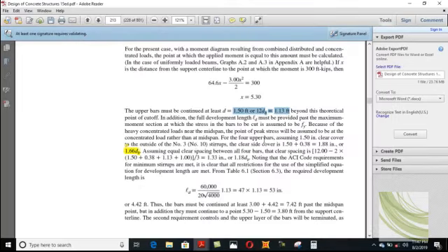Here they say, for the four upper bars, assuming 1.50 clear cover, as usually we did, and they assume number 3 stirrups at a rate of 10 inches, so it will fulfill the criteria. The clear side cover will be 1.50, that is 1.88 inches, or you can say 1.66 db, meaning it's 1.6 times db. Clear? The clear spacing in between the bars is more than db, so you meet those criteria.